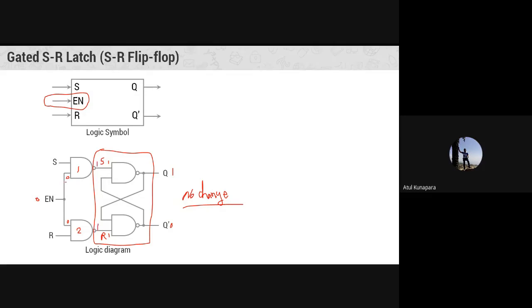Because you can see that this NAND gate can only give you output logic 0 if they both are 1. But as here there is a 0 already coming, they are never going to be both 1, right? And that's why your output is always going to be 1. Same way here also, 0 is coming here, so whatever value of R here, it's not going to be considered.